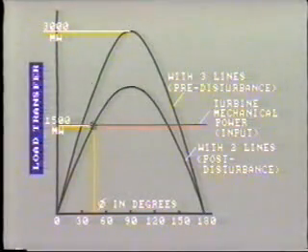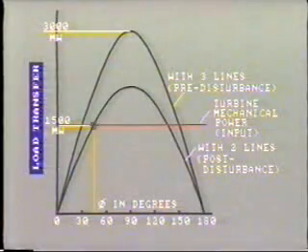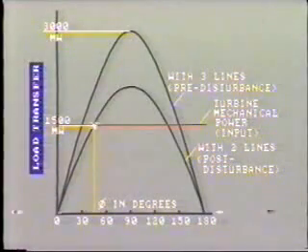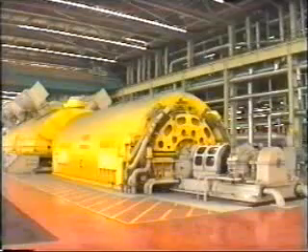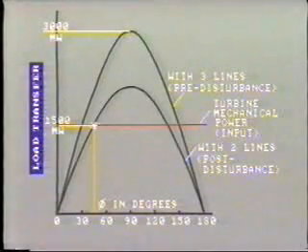Although the reactance of the line has increased, the phase angle has also increased to about 48 degrees. So at this point, we should have equilibrium. But it's not so easy, as we have to contend with the spinning energy of the heavy rotor. The acceleration does not suddenly cease at this point.